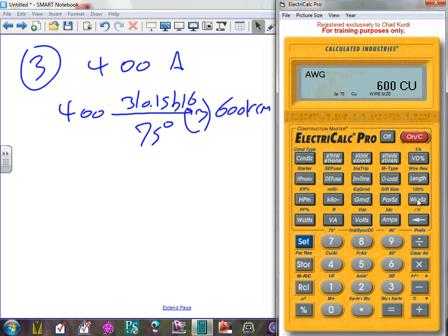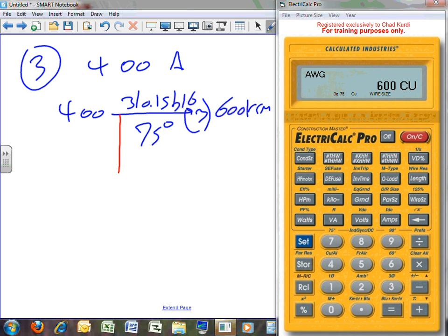Disclaimer, the code allows you up to 800 amps, guys. It allows the conductor to have slightly less ampacity than the overcurrent protection device, if it's a standard one. Based on this rule, you'll see a contractor use, I'm sorry, this should be four conductors with a neutral, four conductors, 500 kcm.